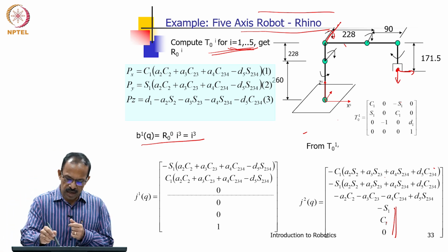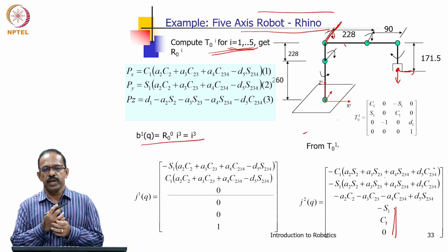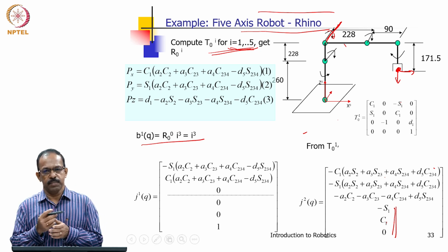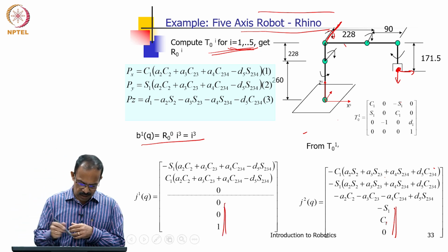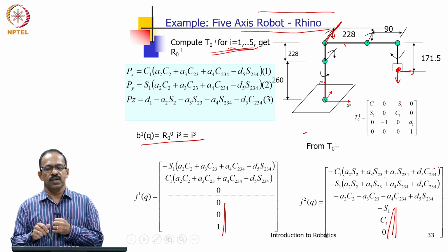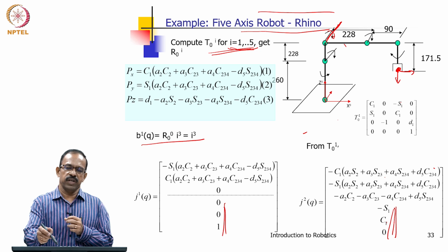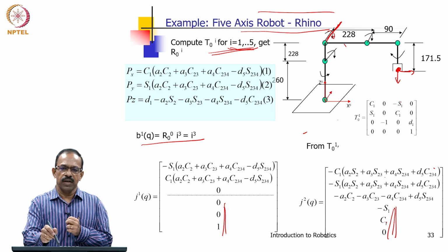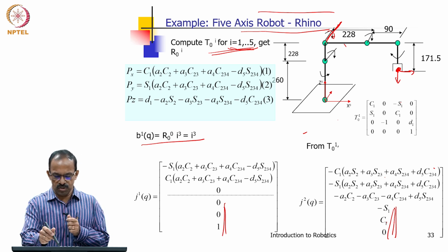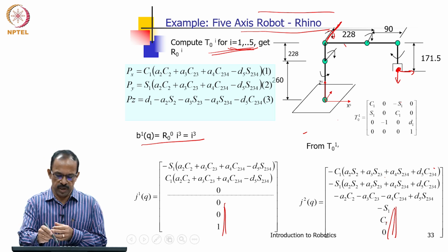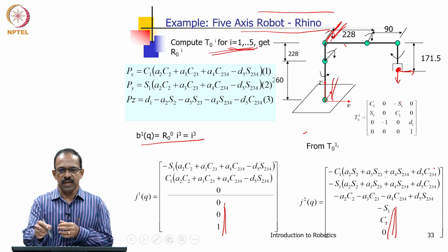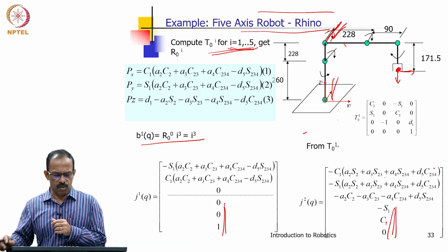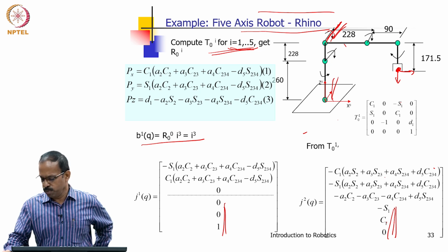So, the orientation of the joint axis with respect to the base frame decides the angular velocity of the tool tip, and therefore we take that as the bk here and write this relationship. This orientation of the joint axis is the one which actually determines the angular velocity. Any change in this angle will affect the velocity here, and as a function of how these two axes are oriented, that is how you get it. So, that is how we calculate the Jacobian for a manipulator.